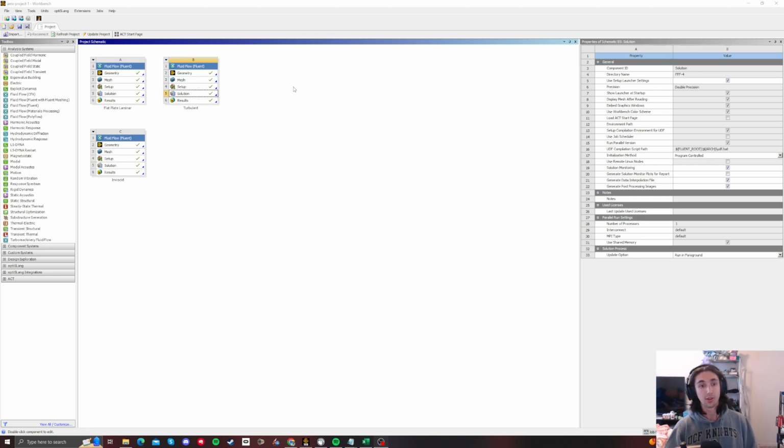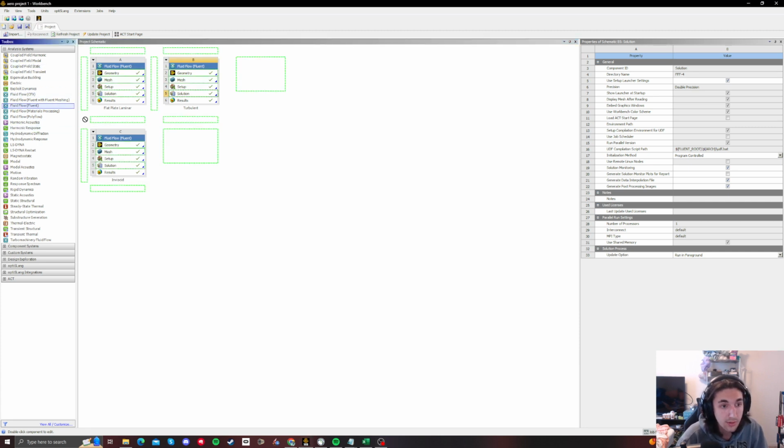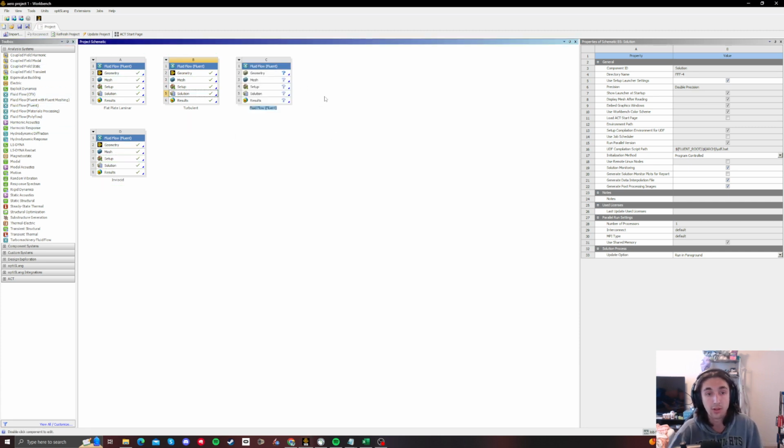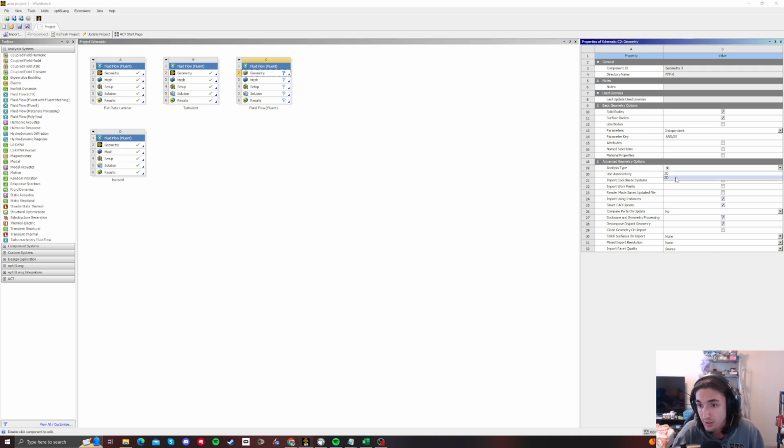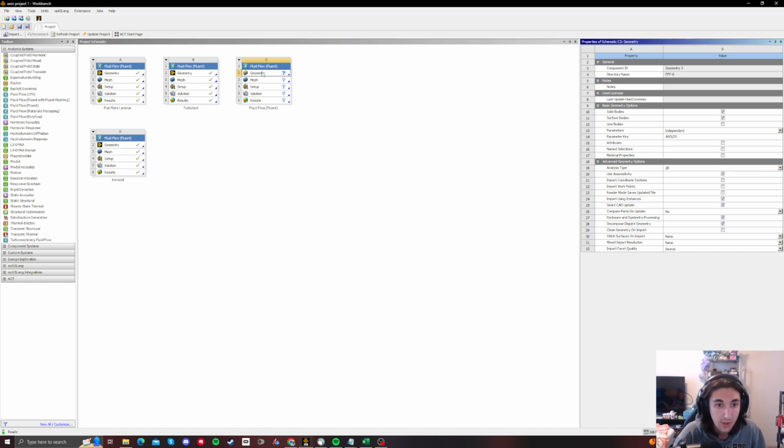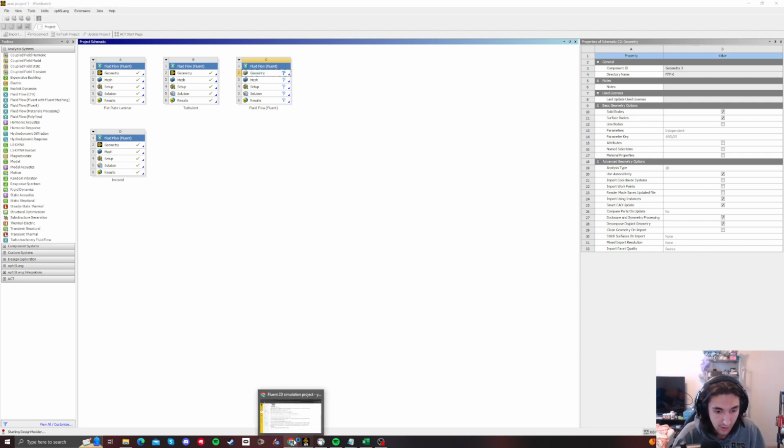So for the flat plate, we're going to go ahead and just drag out a Fluent thing here. If you click on geometry, you'll see over here on the right hand side that we are in 3D analysis. We're going to change that to 2D. Okay, now we are going to use Design Modeler. You can use whatever CAD you want, but this is just what I used last year, so it works out easily that way. It's going to take a sec to open.